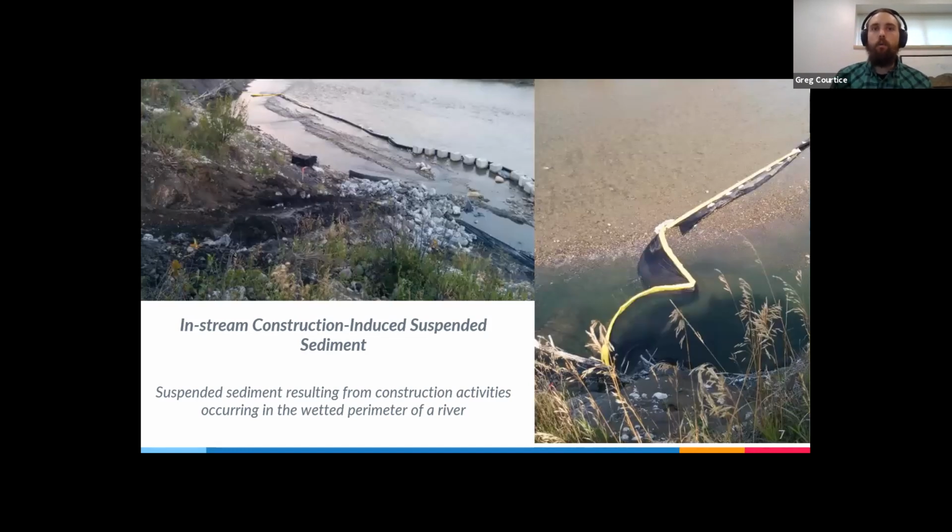So what we have here is sort of typical sediment control measures. It seems like every project has a different specific type of measure that's implemented. Here we've got sort of a compound case of some lock block and silt curtain installation up here, and then just silt curtains down here where it's lower flow.